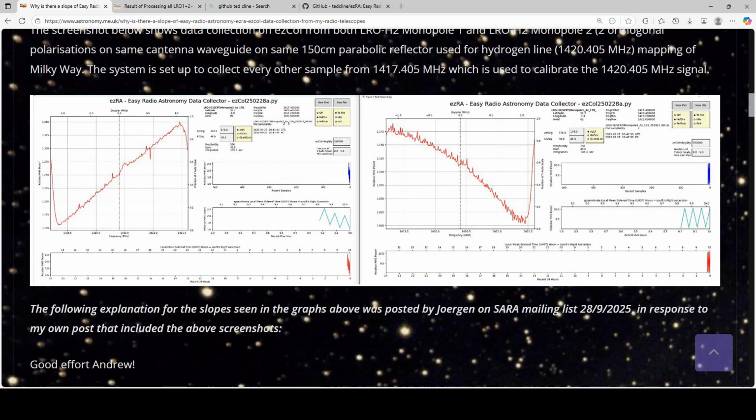When you buy it, it comes with mylar film on it, which reflects sunlight. So you tear that off, and then you spray it with, in my case, aluminium and zinc spray, loads of it, to try and stop it from rusting, which seems to work as long as you keep it well sprayed. And then I put my antenna, which I turn the wrong way around, and use that as a waveguide at the prime focus.